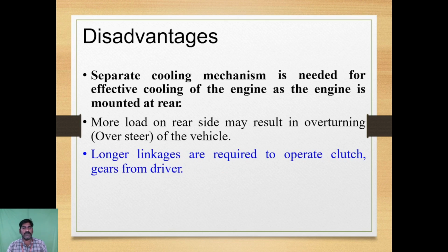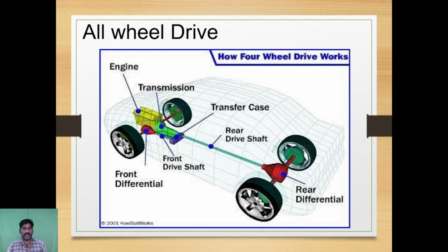Disadvantages: a separate cooling mechanism is needed for effective cooling of the engine, as the engine is mounted at the rear. More load on the rear side may result in overturning of the vehicle. Longer linkages are required to operate the clutch gear from the driver.